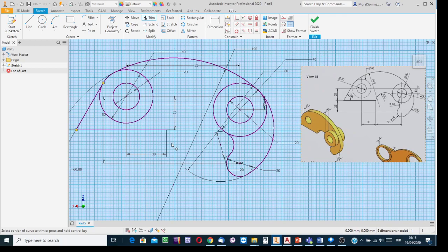Yes, and then the last entity to add to this sketch is this boundary. Okay, in applying to create such a circle, it has only one tangent point. Well, in applying the modern method, the first thing to do is create a circle arbitrarily, and then input it as a dimensional constraint. Diameter is 40.